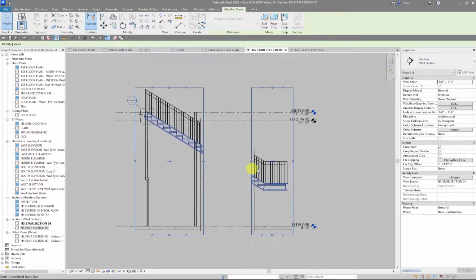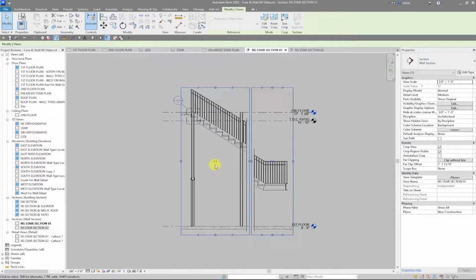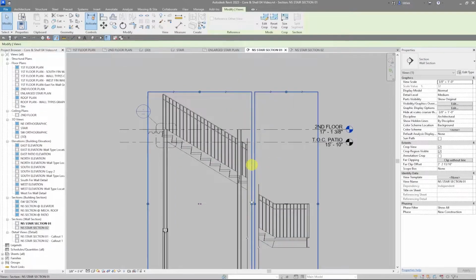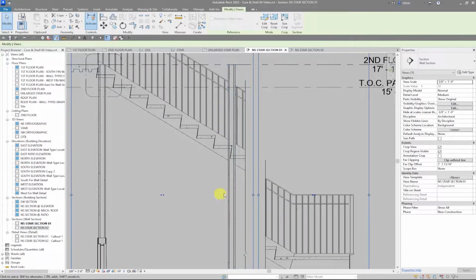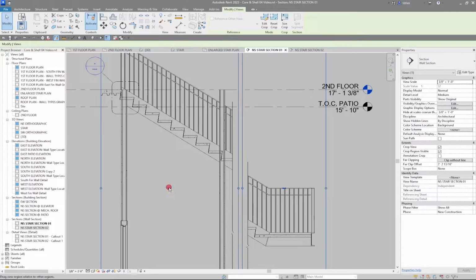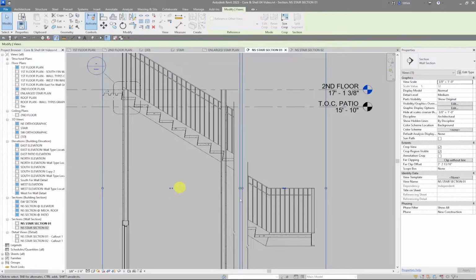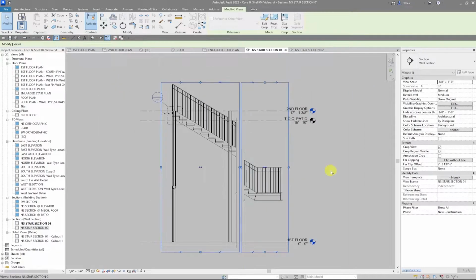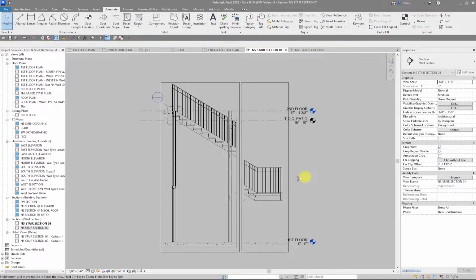Now finally, it's hard to see this one here, but here it's easier to see this little blue arrow that it puts. Just look for them right in the middle of your crop region, and now that allows me to move this closer and actually finally get rid of the space between these two. If you do it too quickly and slam them back together, they will reattach and expand again. So you have to be really careful when you're doing this, when you want to get them really close together like this. That should be good enough to fit on my sheet.